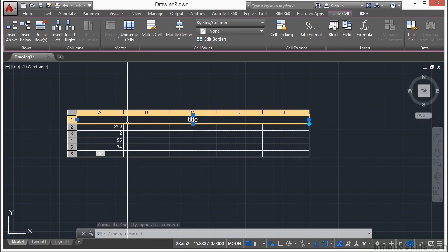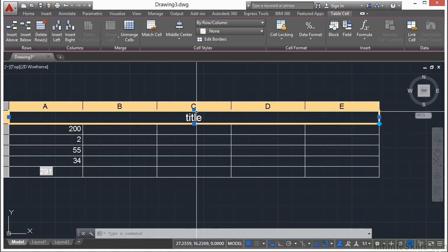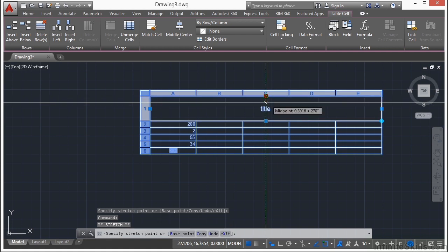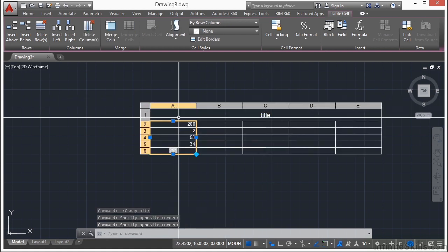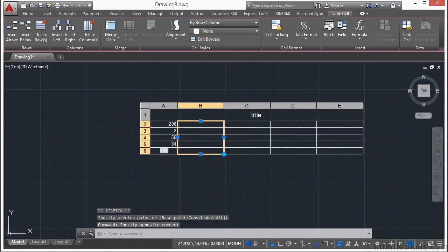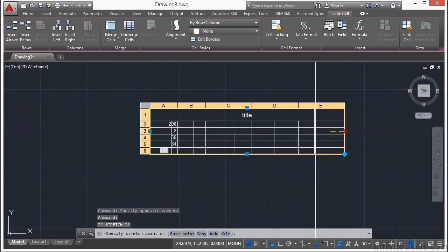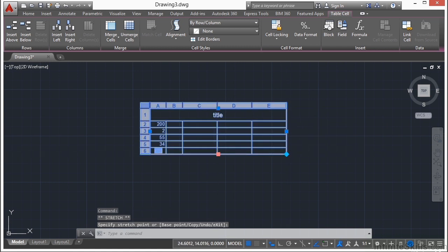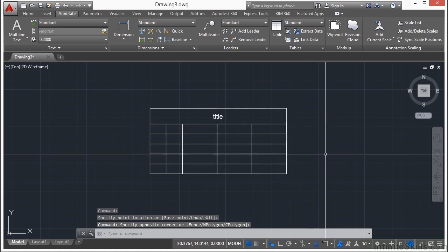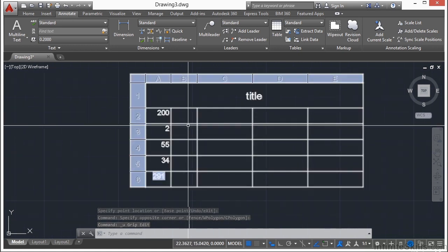You can manipulate your table with grips. So you can see here, you have a left, right, and some other tops and bottoms. Now the left and rights kind of act like stretches, and so does the up and down. If you click on the top of a column, you can stretch those different column widths. If I select this top box here, I pick everything, and then I can change the overall width or height. If I click here, it will automatically fill the cell, and that can get you into trouble sometimes, but a quick undo will set things back. So you can do things like that.